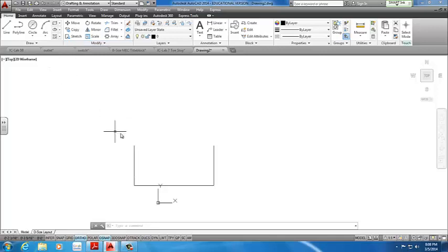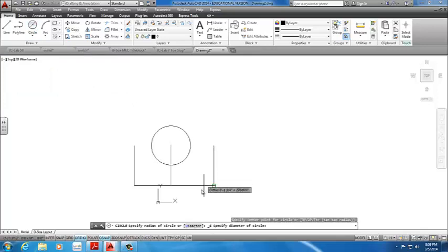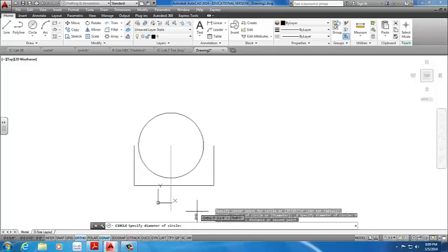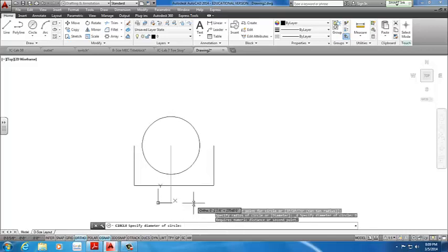Our next part is we need to create an arc. There's a few options. You can use the arc command, or we can just use a circle. I'm going to use the circle. It's pretty simple for me. So circle, diameter. So I click here for diameter. In 2013 and 14, they gave you that option of just clicking on these commands. So now you can just use one hand and pretty much do everything instead of using 2 hands. Diameter, and we're going to type in 4.